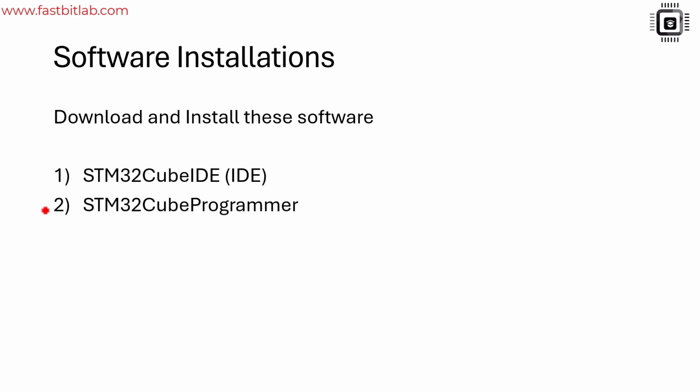Then I would also suggest you install this software, STM32 Cube Programmer. This is not an IDE. This is just a software which communicates with the microcontroller over several interfaces like UART interface, USB interface, SWD interface, like that. Basically, it can talk to the bootloader of the microcontroller to program the microcontroller. A very helpful tool. It has a lot of capabilities, but this is not an IDE. This is a programmer by using which you can program the microcontroller without using any onboard or off-board debuggers.